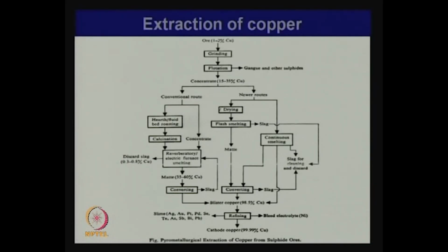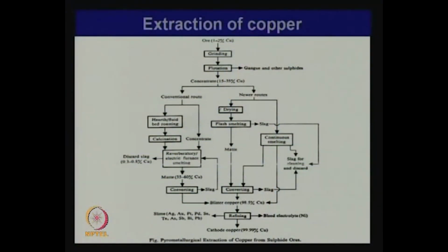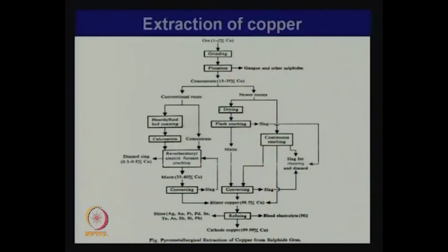The main idea is to oxidize the concentrate, so that most of the iron sulphide is taken to the FeO stage, preferably not beyond, because if it goes beyond FeO, then subsequently we will find it difficult to remove it through slagging. So, to ensure that it does not get over oxidized, we have to leave a lot of iron sulphide unoxidized. It is okay. Now, this is an oxidizing step. You need oxygen to oxidize the concentrate.